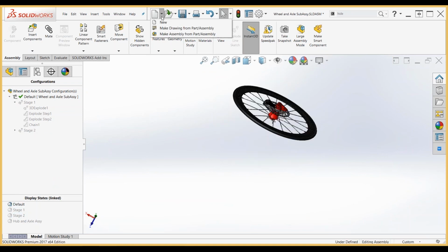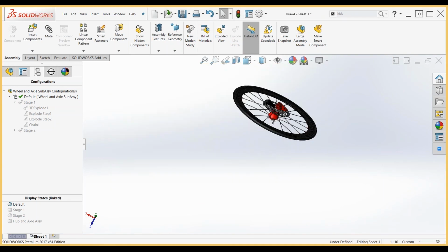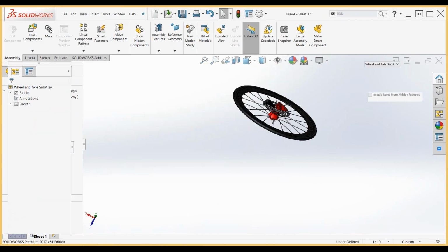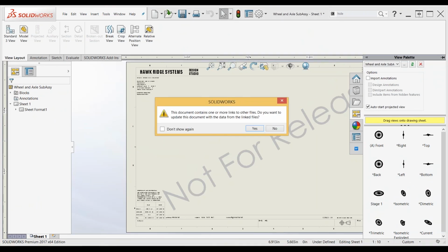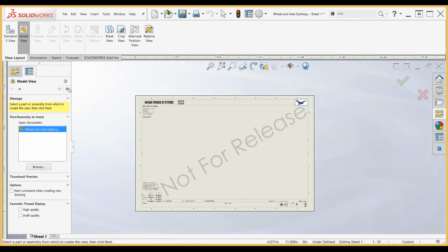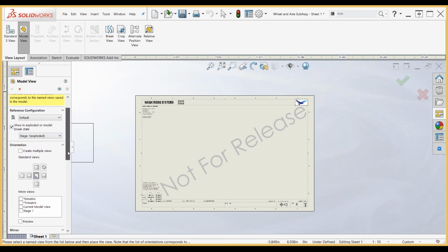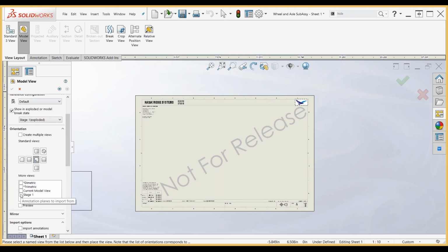But there's a way that you can do that completely inside the drawing. So I made myself a section view right here, just the standard way using my section view tool. But if you right-click on the section view, you have the ability to generate an isometric section view. So I'm going to click on that, and we can see that it has, in fact, given us an isometric view of that section that I created.